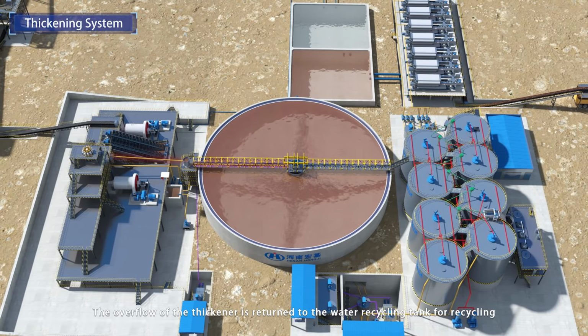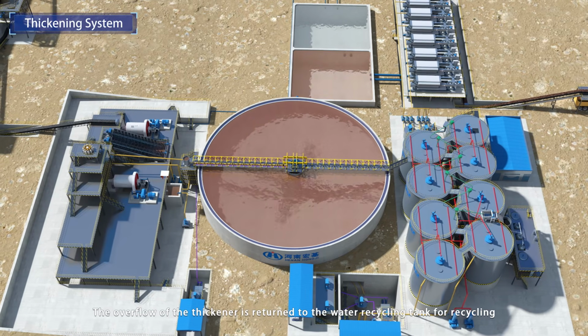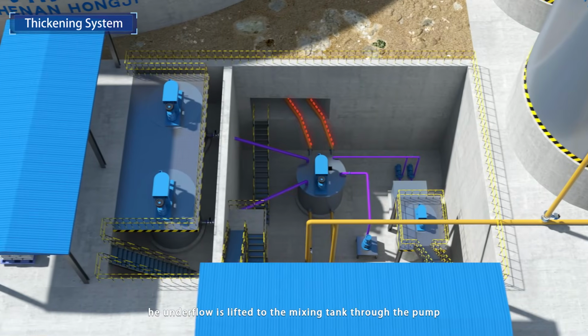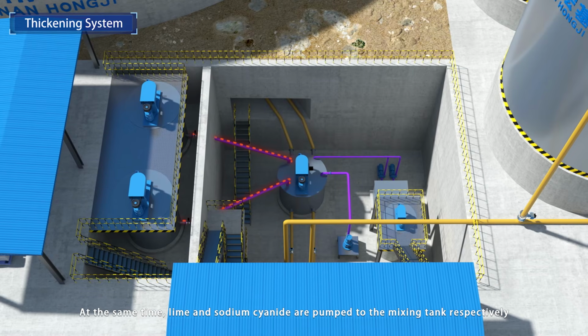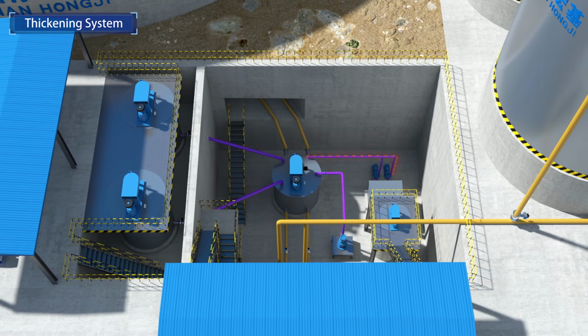The overflow of the thickener is returned to the water cycling tank for recycling. The underflow is lifted to the mixing tank through the pump. At the same time, lime and sodium cyanide are pumped to the mixing tank respectively.